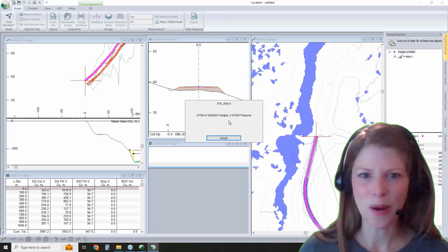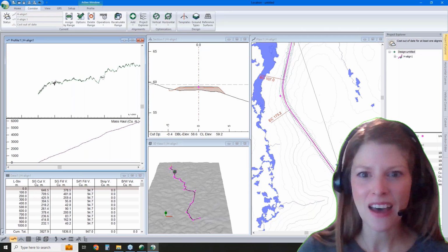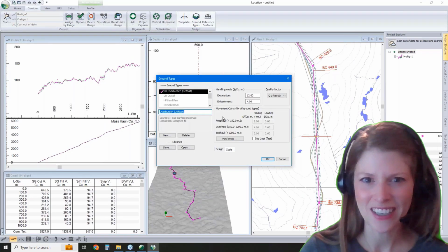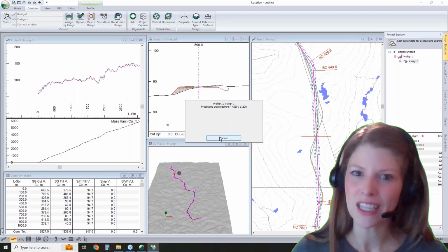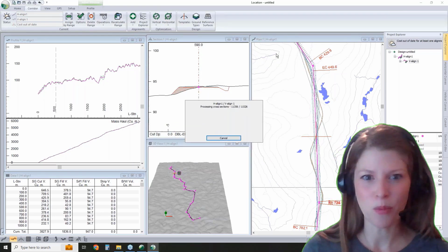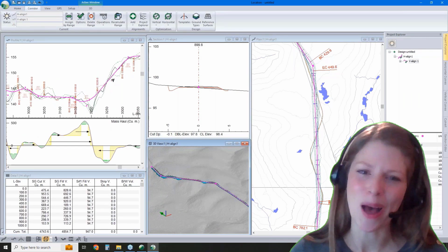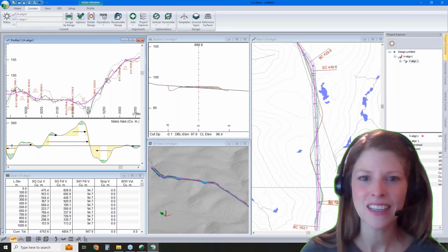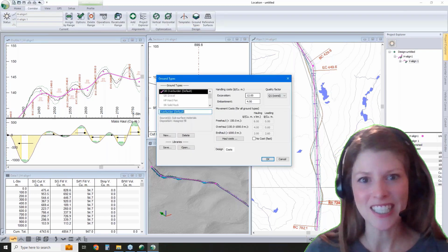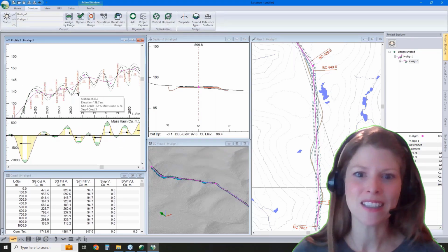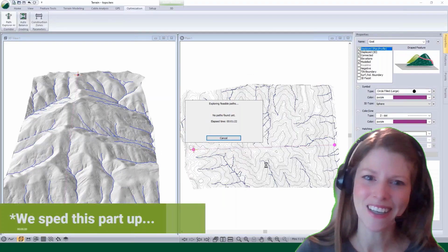So here, in the webinar, we set up our project. We brought in our Path Explorer path that we selected, defined our cross section, and used two different tools. First, the Polyline to alignment to convert it into a proper alignment with curves. Then we went and did some vertical optimization on it. So here at the vertical optimization, we were minimizing at a much greater detail all the different cuts and fills, balancing our earthworks.